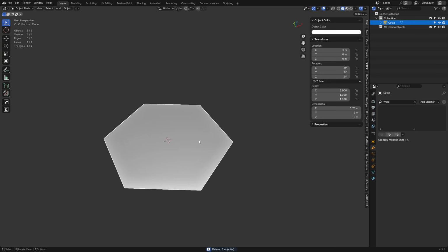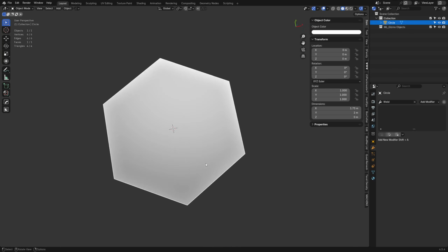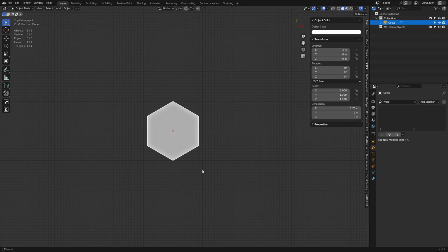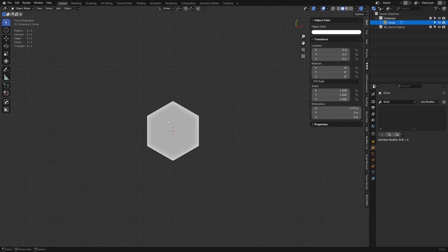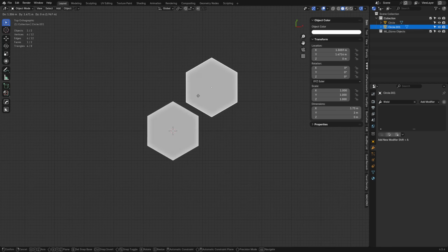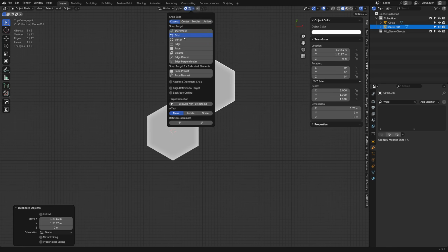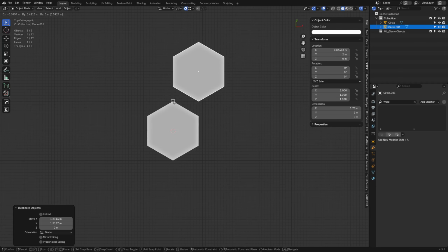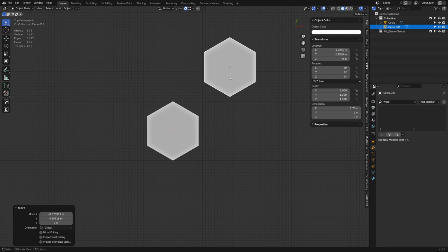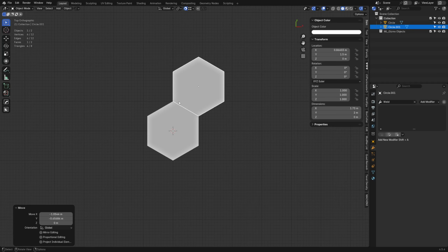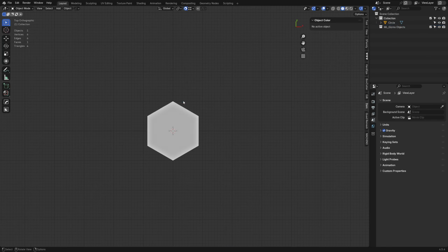Also do booleans into it if I wanted to, but here's the thing. The other type of video you're going to see is people show you how to model or start creating this pattern by just doing something like Shift D and duplicate. Might use snapping, vertex snap. Now here in Blender, vertex snapping on the object level at least does this number. It used to be a problem everybody wanted fixed basically, but they fixed it. So it's G now. You hit B, and you can actually select the vertex and snap one object to the other. You could do this like this still, it's fun.